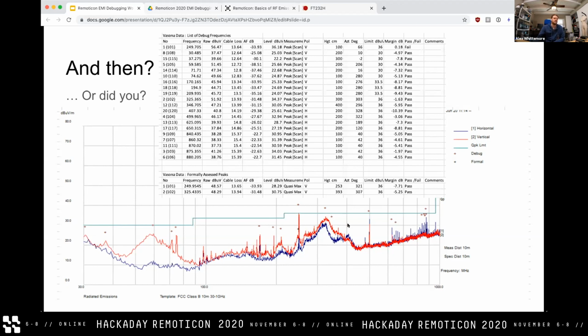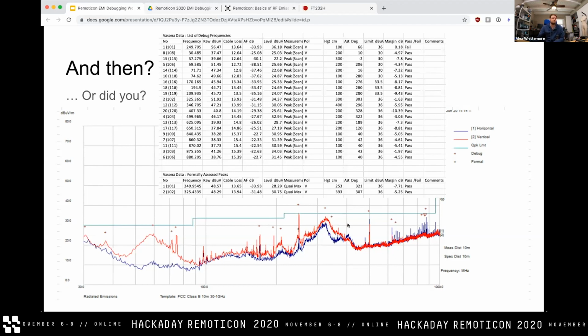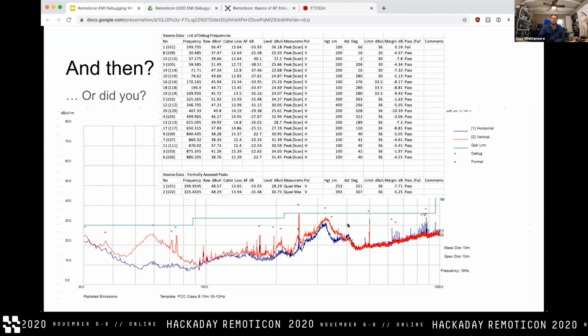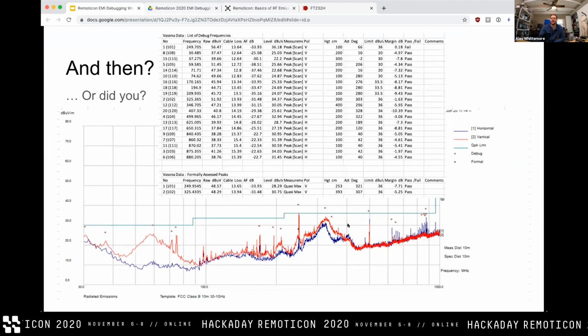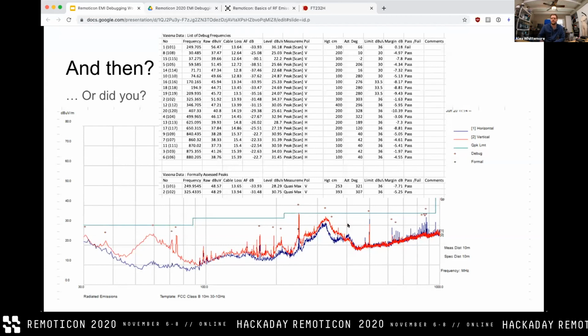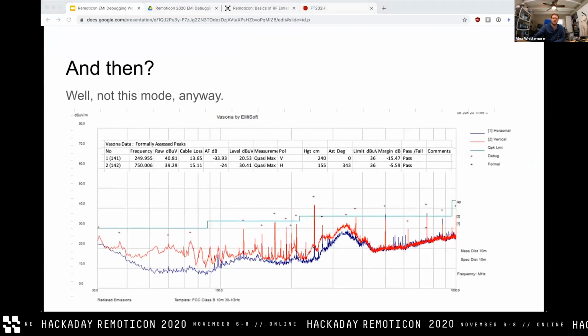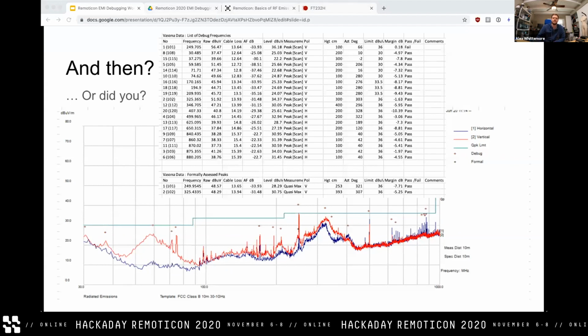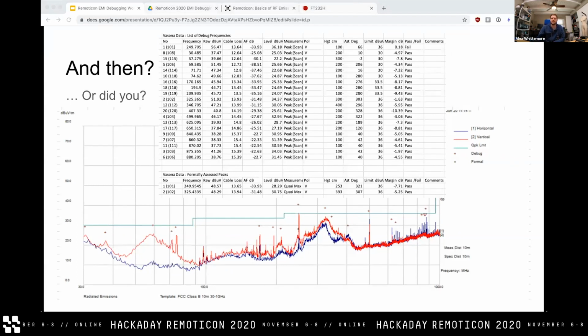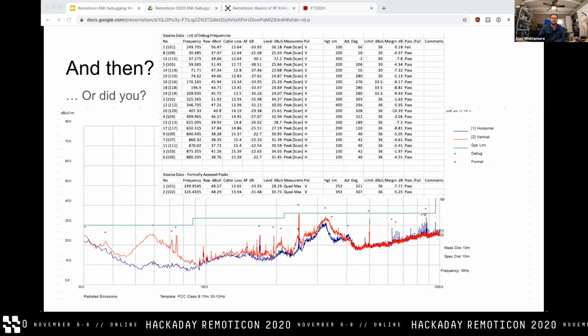And it turns out that this device performed just fine under wireless conditions because there may or may not have even been an Ethernet cord plugged in. And as I'll describe later, or right now, I guess. This device basically only fails its emissions testing under connected to Ethernet conditions.